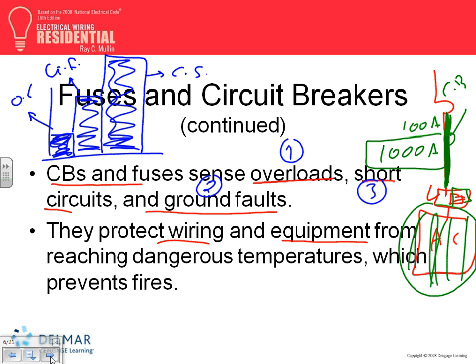They're all current. The reason I say that is because some of you will at one time be working with overvoltage, undervoltage, or underfrequency protection. There's a lot of protection, guys, other than overcurrent. Overcurrent is only one type of protection that we do in the power industry. There's under/over voltage, under/over frequency, directional current, tons of other protection. The most common protection is the overcurrent protection. It uses a fuse or circuit breaker.